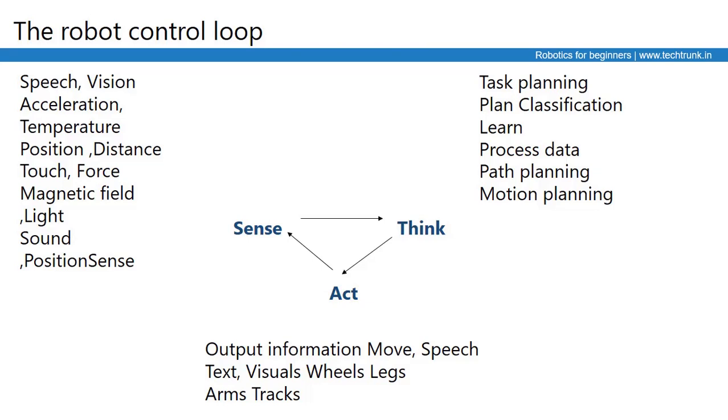So a robot needs to have an idea about itself and an idea about the environment. The idea of the environment is given by external sensors. The idea about itself, the machine's inside architecture, the speed and so on, is given by internal sensors. So the first thing in the control loop is sensing capability. Sensing creates information which is fed to an algorithm. The algorithm does some processing, and that enables actuators to perform actions. So after sensors we come to thinking, and from thinking to actions.